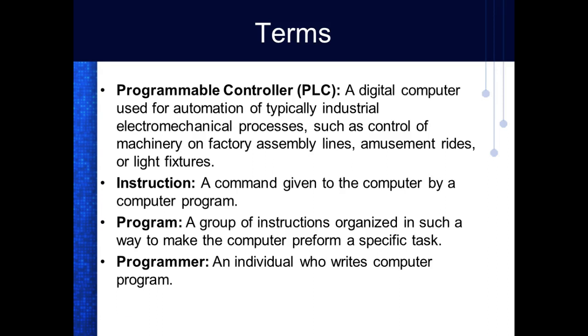Machine language is the binary language of the processor. It is ones and zeros. The only thing this processor understands is ones and zeros. So the processor is basically in two modes. It's in the fetch cycle. In the fetch cycle, whatever binary number comes in, it considers to be an operational code, an instruction. Then it switches to the execute mode, and it does what the instruction told it to do. And then it switches back to fetch. Fetch, execute, fetch, execute. So we have a big list of operational codes, and they're all binary.